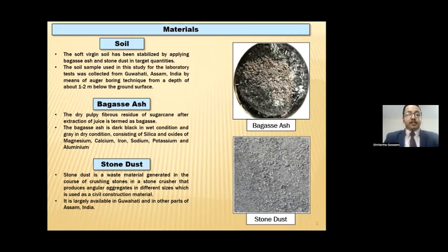The particle size distribution performed by sieve analysis and hydrometer tests indicated that the soil can be classified as well-graded silty clay. And the PSD curve is presented in the following slides.